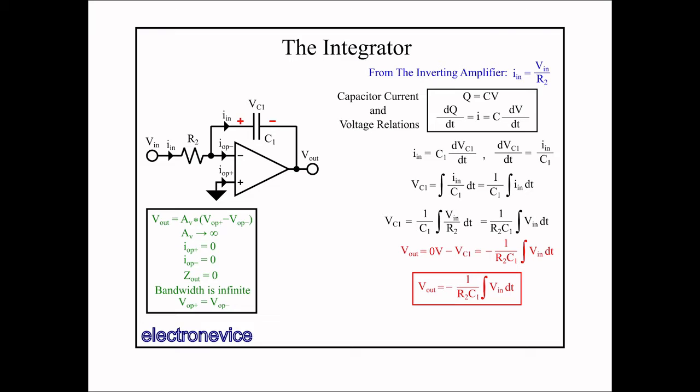This kind of circuit can be useful for filtering signals with unwanted fast-moving content or garbage that should be ignored, dulling signal edges by attenuating the high-frequency content, or for implementing the I portion of a PID control loop in the analog domain. In the past, it was also used as an integral calculator, where the input signal was the function that you wanted to know the integral of, and the output voltage versus time was measured to see the result. While the time domain analysis of this circuit is illuminating and instructive, it is generally more useful to analyze it in the frequency domain, which we will do now.